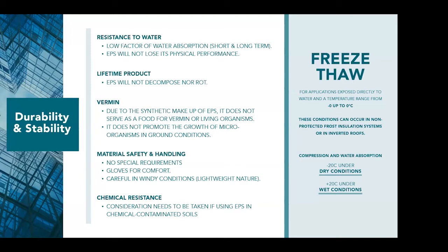Just something to be aware of, something that we consider, but the resistance of EPS to freeze thaw is very, very high. We look at EN 12091; this standard measures the compression and the water absorption under conditions from -20 to +20 in wet conditions. And EPS performs very, very well in that.